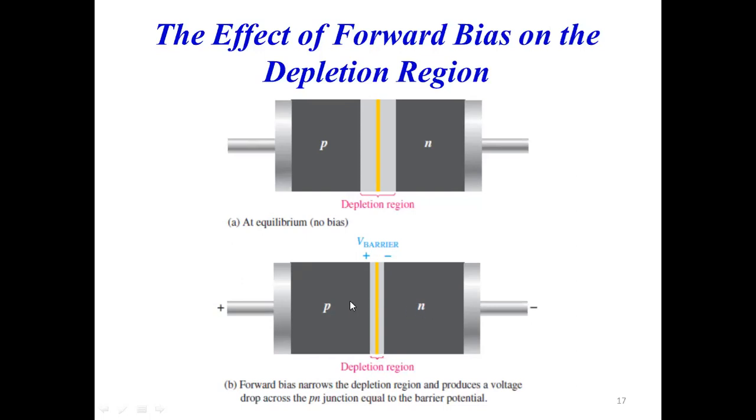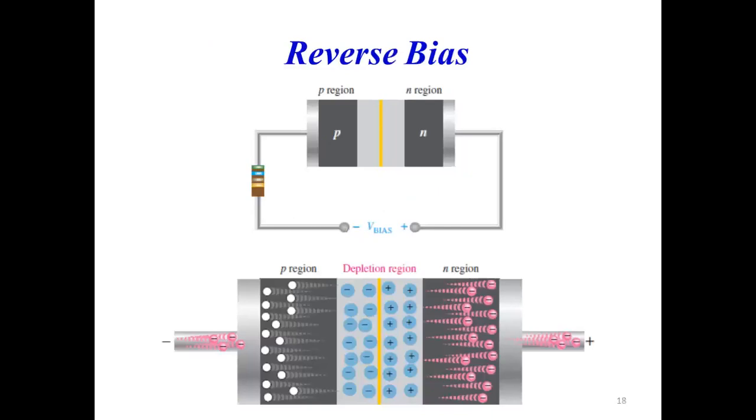So obviously, it will reduce your depletion region. So this is the depletion region. Just see here, the figure shows a reduced depletion region with forward biasing. The positive terminal is given to the anode with positive potential and the cathode is connected to the negative terminal. Is that clear? Now, let us see how to reverse bias a diode.